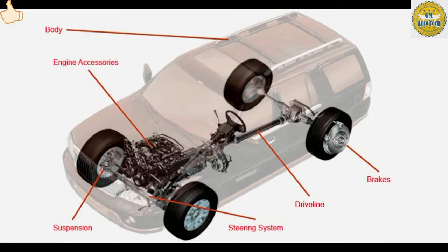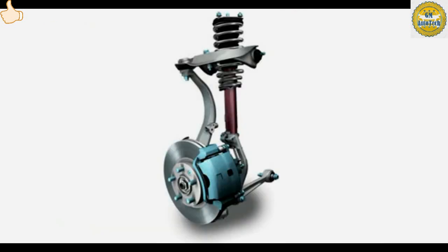The suspension system is a common cause of vehicle noises. Control arm bushings, springs, shocks, and struts are all susceptible to wear, which can result in noise. A shock or McPherson strut can cause noise due to internal damage or improperly torqued mounting hardware. Leaf springs can cause noise if they come in contact with each other or have a missing leaf tip insulator. On coil springs, a damaged or missing isolator can also cause noise.